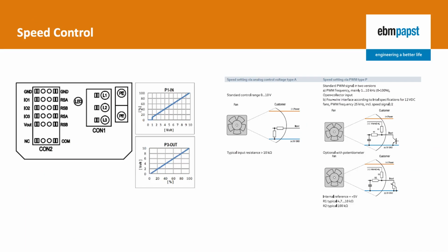Our smallest products, we offer 0 to 10 volt DC or PWM analog inputs, along with optional built-in temperature controls. Our larger motors, we offer those and more, 4 to 20 milliamp, up to 3 separate digital inputs, a built-in PID control loop, and Modbus communications. If the customer prefers BACnet, we can provide a gateway to that as well.